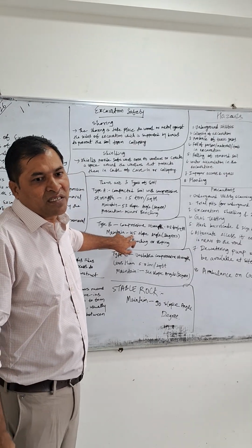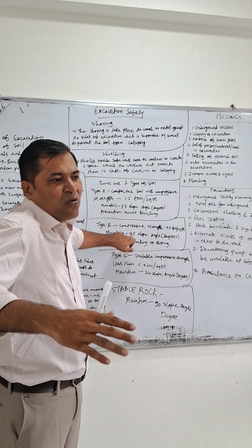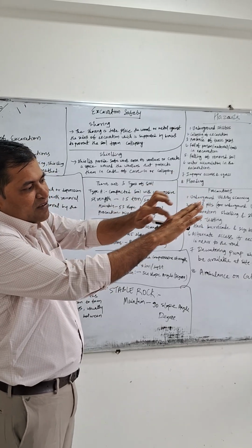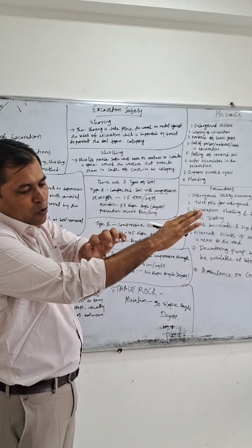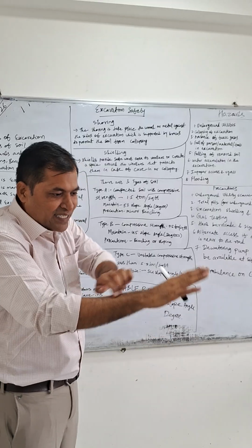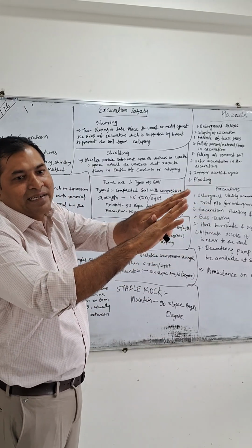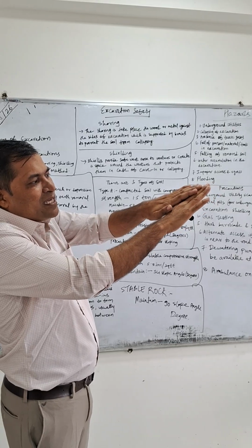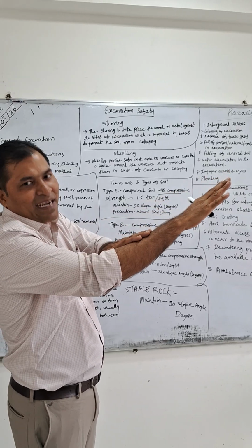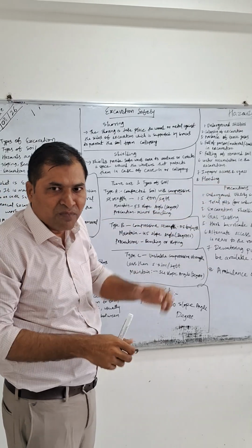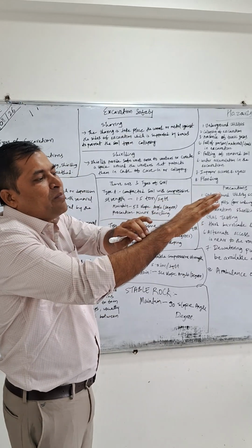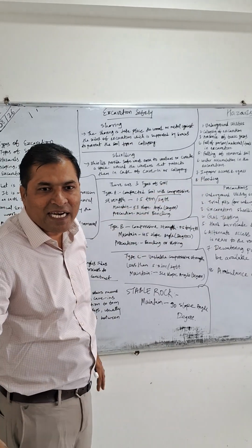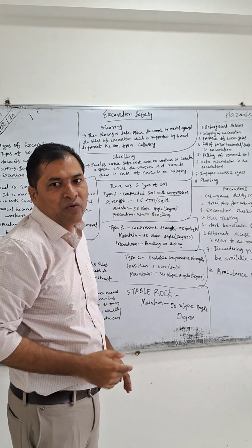If the compressive strength of the soil is lower, you can go with a 45-degree angle. So the workers will always go with the help of a 45-degree angle. They will go down. They can work over there and then they can come back with the help of the same area. So always do the excavation with a 45-degree angle. You are removing mud, but you have to remove the mud from the downside and make a slope as well. If any kind of emergency occurs, you can go out immediately.